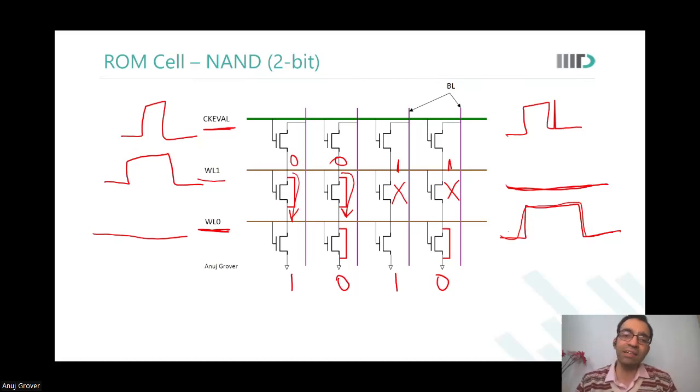So ROM cells are very, very dense, which means that there are huge coupling capacitances that will come between these bit lines. There are many other additional variables that can appear when there is a particle strike or anything, and that can really bother you. So you want to keep as many things in control and fixed.